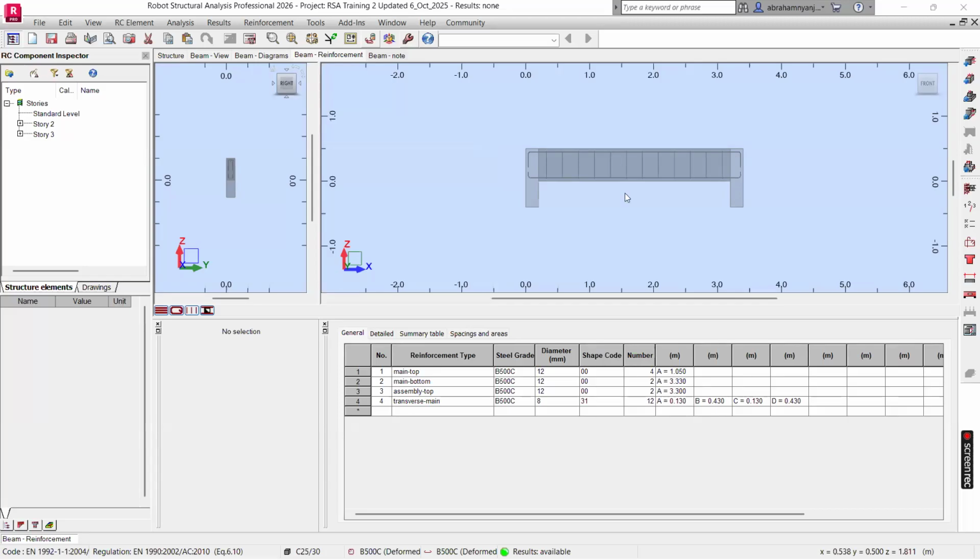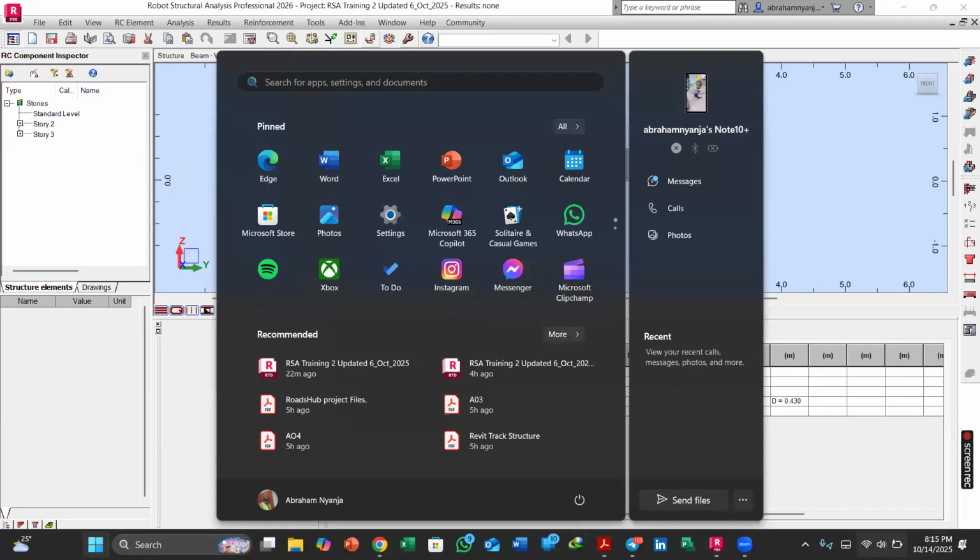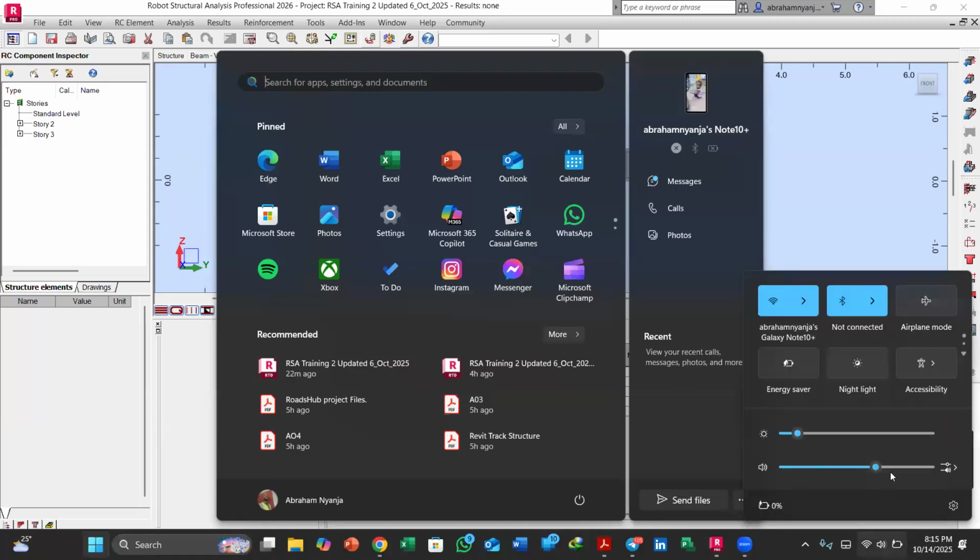Maybe you don't get my question. You haven't shown us the worst case scenario load that is acting on the beam. If you are to design manually, you have to see that load that comes from the analysis, then use it for the design.